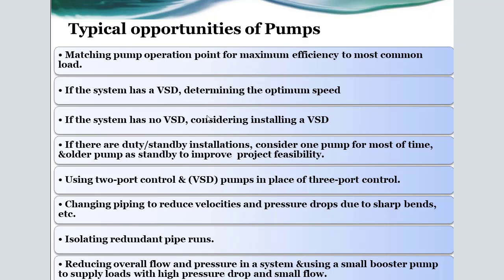There is also the opportunity, if the system has a variable speed drive, to determine the optimum speed, and if the system has no variable speed drive, the energy auditor may advise considering installing variable speed drives on these pumps.